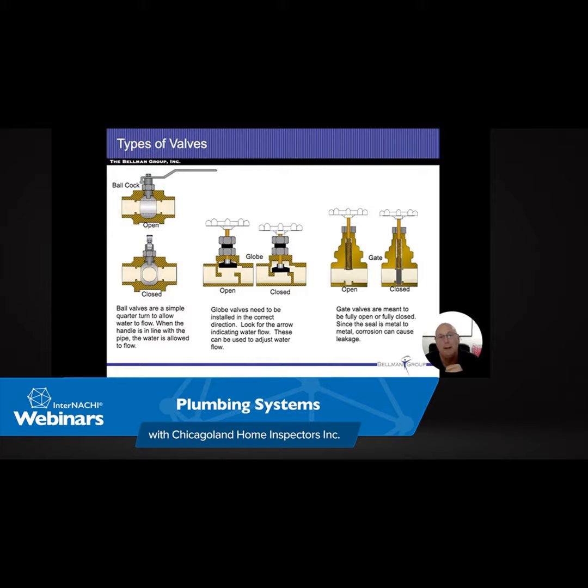I think you're going to find that when you open up sprinklers on the outside, and I'm talking about the valve itself, they're switching those over to be quarter turn valves now for all the newer ones. But in the old ones, we had a whole bunch of turns coming on them. And as you open them up, you start getting that water hammer or that vibrating. And that'll continue until you open it up all the way.